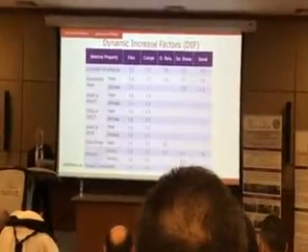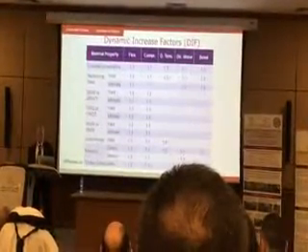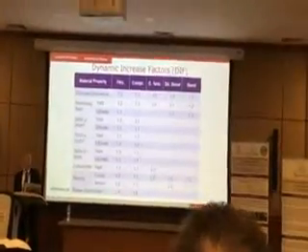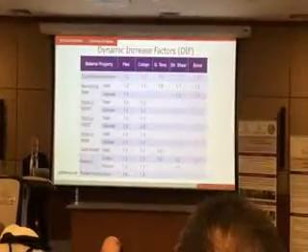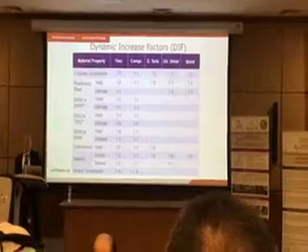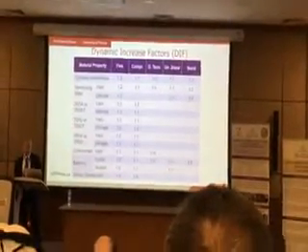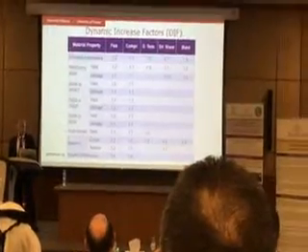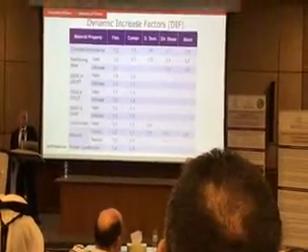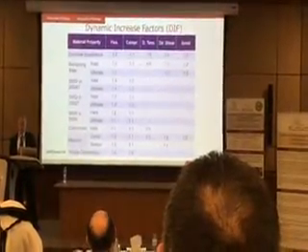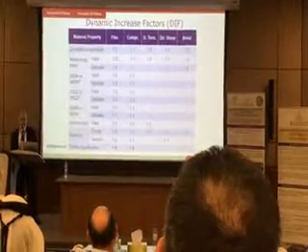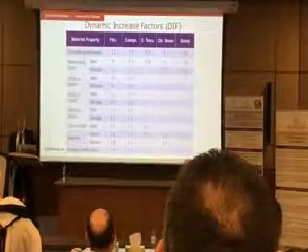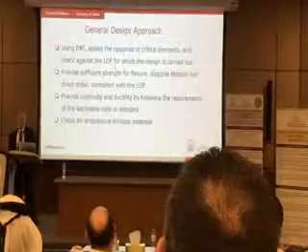So these are the tables now I will show you for flexural, concrete compression, axial compression, diagonal tension due to shear. As you can see, we are permitted to increase concrete strength 10% to 20% to account for the dynamic increase factor or strain rate effect, and steel yield strength again to 20%.